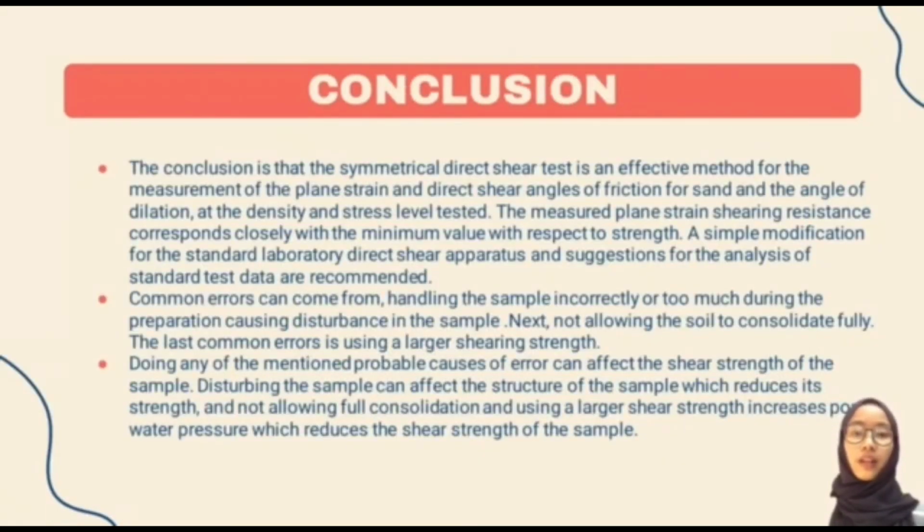In conclusion, the symmetrical direct shear test is an effective method for the measurement of the plane strain and direct shear angles of friction in sand and the angle of dilation at the density and stress level tested. The measured plane strain shearing resistance corresponds closely with the minimum value with respect to strength. A simple modification for the standard laboratory direct shear apparatus and suggestions for the analysis of standard test data are recommended.